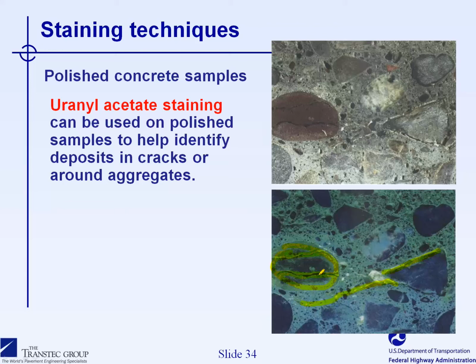Okay, thank you. The next question: as you show the ASR gel filling the air entrainment voids, does this then eliminate the benefit of air entrainment in the concrete? Yeah, this has been mentioned as a possibility. The air voids that are the most useful for freeze-thaw prevention are the very, very fine air voids. So those air voids are not necessarily those that we see being filled by ASR reaction products.